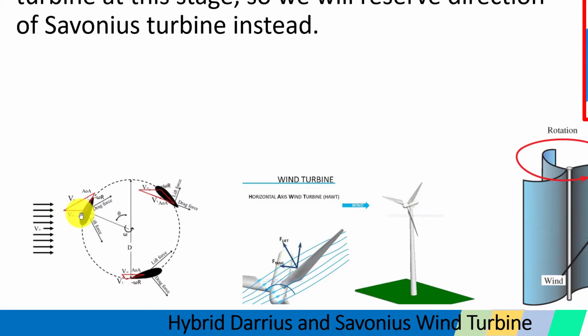If we apply the principle of the velocity triangle, the second vector would be the velocity of this turbine. And you can see that this is minus omega r. Basically, if you just place a value, this will be pointing in this direction. So it's a minus omega r, and the resultant is pointing in this direction. So the flow is pointing basically in this direction.